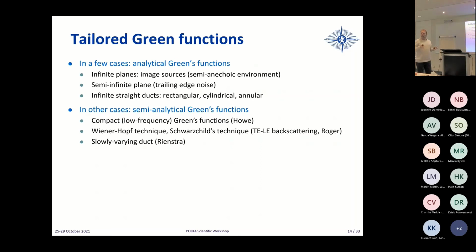Yeah, by the way, acoustic compactness, familiar concept? Definition is? Like when your length scales are way smaller than the acoustical wavelength. Okay, so if your scattering body is small compared to the acoustical wavelength, then you can effectively make this compact assumption, and then you have this thing here. But again, there is an assumption.